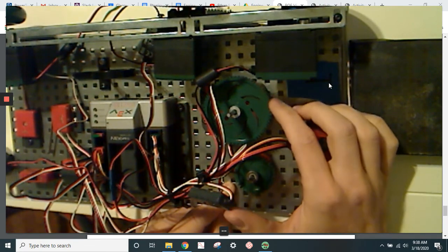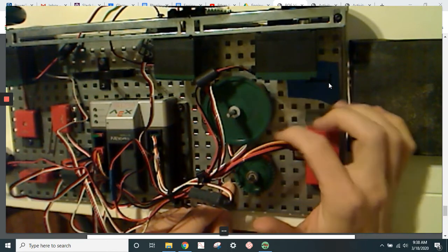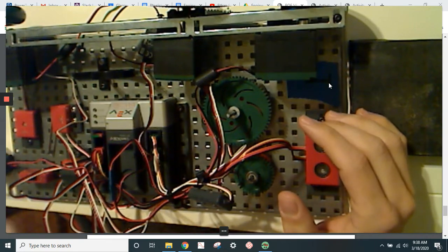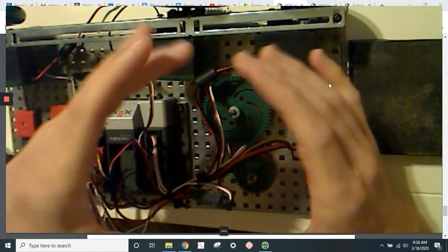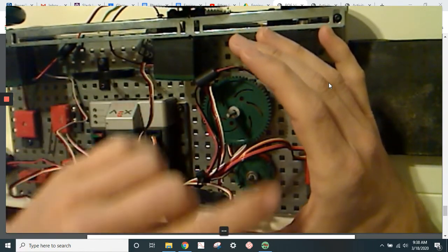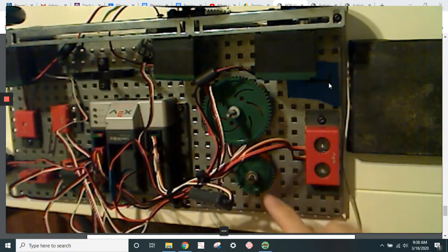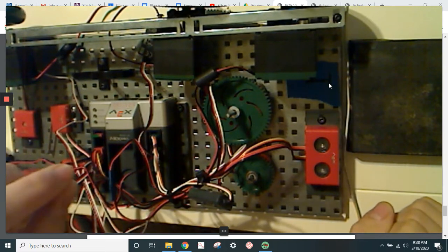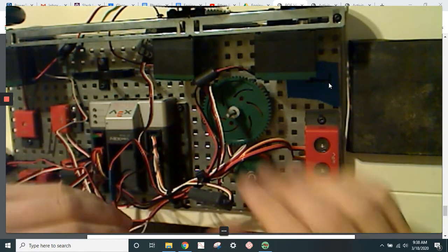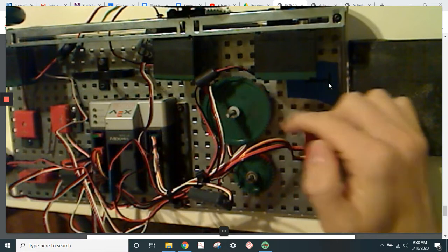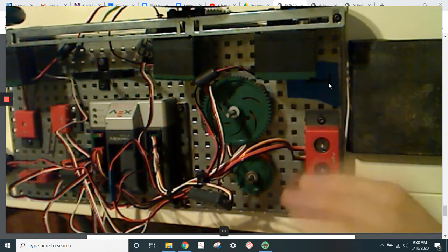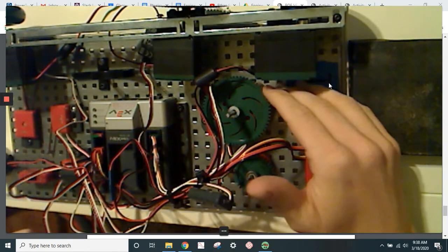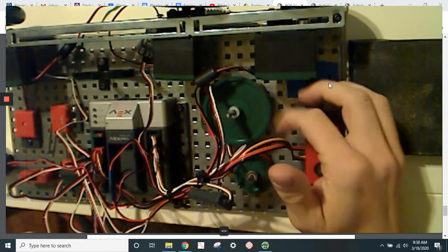This next guy is a Quadrature Encoder. This is just a free spinning thing. On the inside of this little box, there's a little circle that has 360 little slits in it. There's a little light that goes through here, and it counts how many times the light gets let through by those little slits. So if I spin this one full spin, it counts 360 of those slits being passed. And so this can actually count how many degrees something is turned.